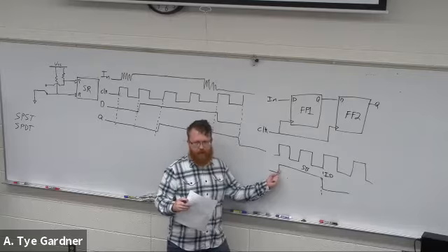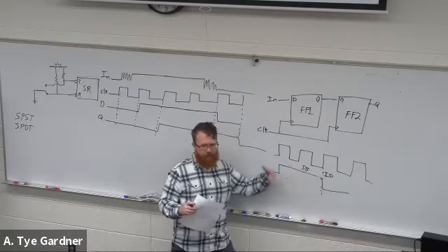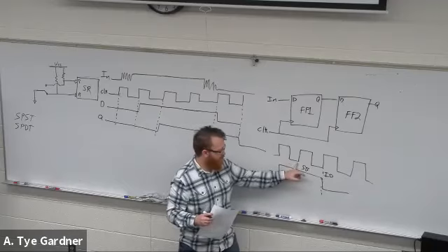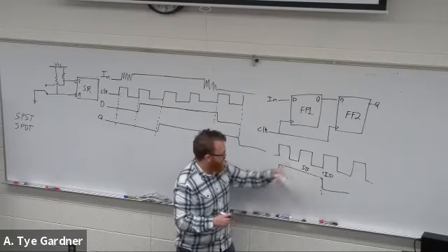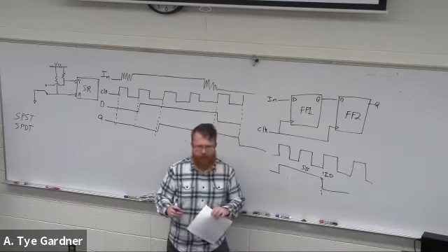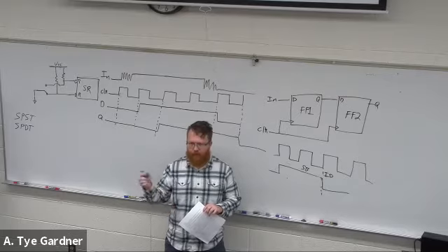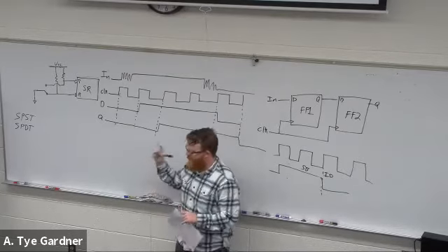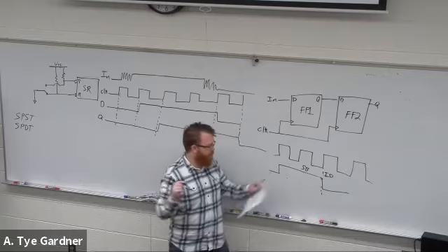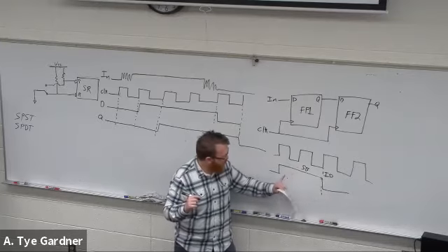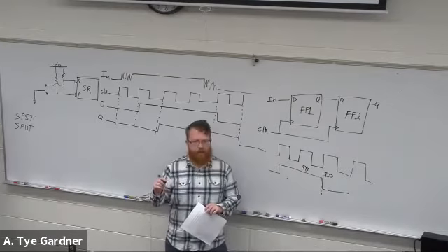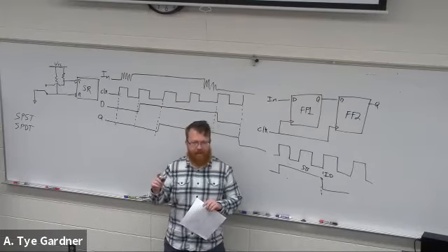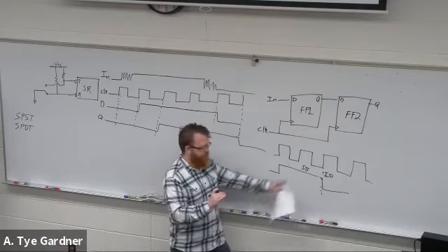And at the same time, we're going to say, hey, our next state needs to be idle, and we'll eventually transition, and your rising edge ends up lasting for 2 full periods. If you go and look at your timing diagram, there is a way that you can do it in one. This way is going to simplify it. In fact, everyone I've looked at will do this, more or less. Did you say yours is 1? Okay, yeah, so it is possible to do that. Most people end up with 2.